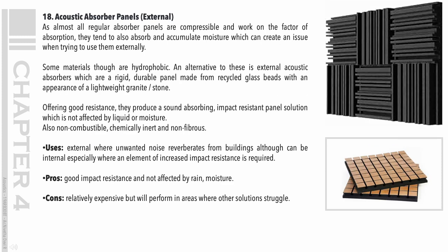18. Acoustic absorber panels, external. As almost all regular absorber panels are compressible and work on the factor of absorption, they tend to also absorb and accumulate moisture, which can create an issue when trying to use them externally. Some materials though are hydrophobic. An alternative to these is external acoustic absorbers, which are a rigid, durable panel made from recycled glass beads with an appearance of a lightweight granite stone. Offering good resistance, they produce a sound-absorbing, impact-resistant panel solution which is not affected by liquid or moisture. Also non-combustible, chemically inert and non-fibrous.